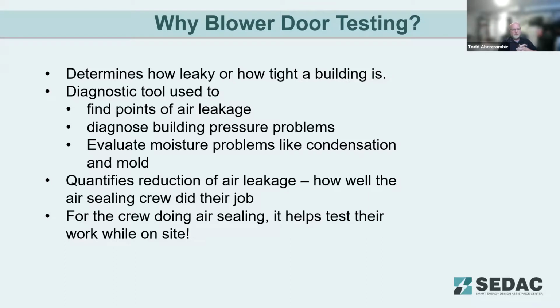And some working crews, some installation crews, can actually use the blower door test during the job while they're air sealing. In the right situations, they can hook up the blower door and do the air sealing work and literally check their work before blown insulation or wall insulation is installed or whatever. So you can help test your work while on site.